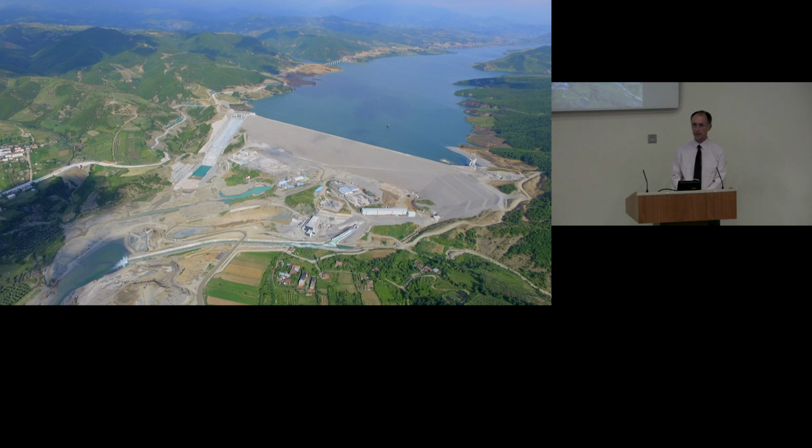And then the next thing was to make sure that the grout curtain was adequately QA/QC'd, and extended to the right amount, so that the flow path for anything getting round that end of the dam was so long that it wouldn't have a destabilising effect. But absolutely, it was a concern with all that movement and the lack of integrity of that material, for sure.